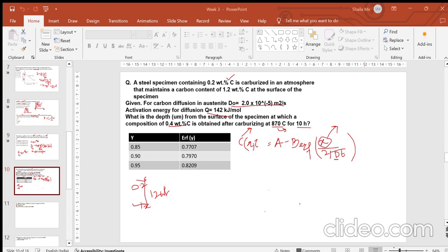I just want to emphasize the scale. It is a very small distance over which you have been able to achieve a carburization of 0.4%, because the outside is 1.2, so it is almost half, 50% of the carburization has happened, but at a very small scale. You have to understand that these processes are occurring, the diffusion is occurring, but you are not carburizing the whole surface. This is surface hardening only. The magnitude of the surface layer is very small, yet that is making a huge difference in your properties and in your further mechanical effects.